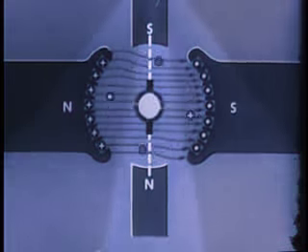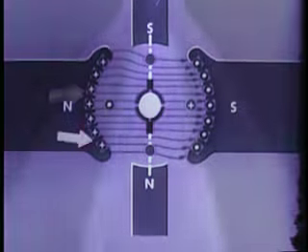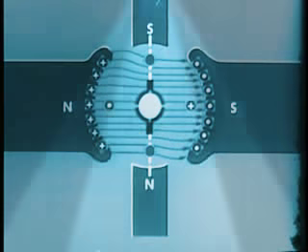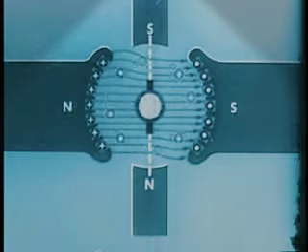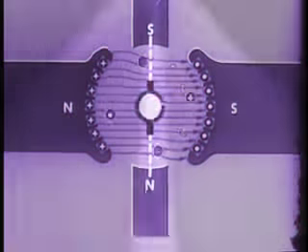In addition, to further counteract armature reaction, windings called compensating windings are sometimes placed in the main pole faces. The current in these windings is armature current flowing in the opposite direction to the current in the armature conductors. Magnetic fields in DC generators may be produced by electromagnets or permanent magnets. Permanent magnets are used in relatively small devices like a field telephone ringing generator. In larger generators, the field is created by electromagnets.